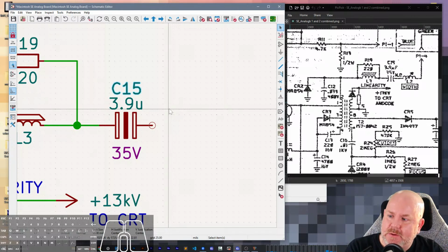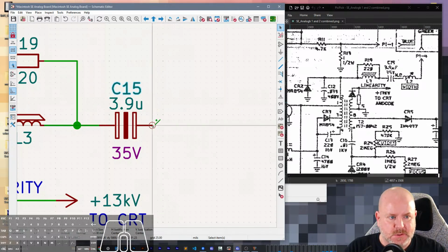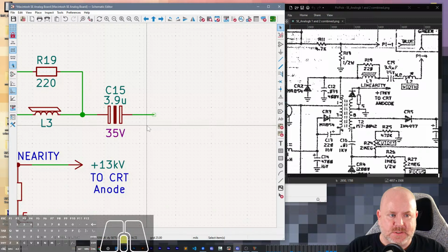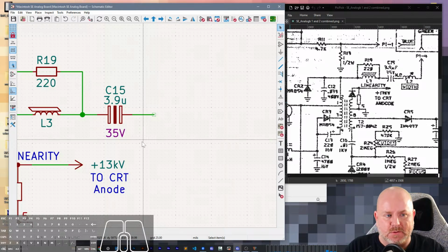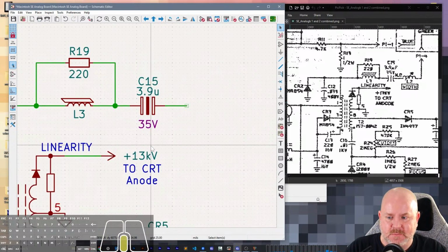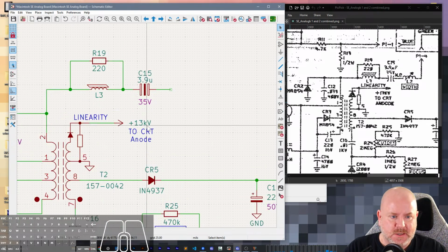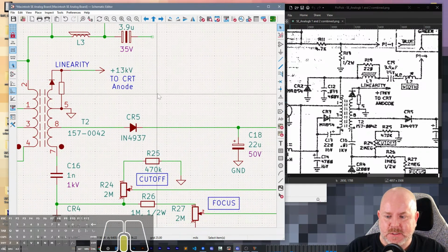The other place you'll see bipolars is audio, and RS-232 has bipolars as well, generally to handle the positive and negative voltages in RS-232. In those cases, the ripple current capability isn't nearly as important, because at least in the case of RS-232, they're not really handling much.